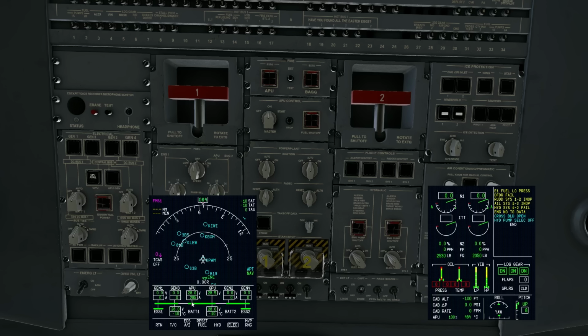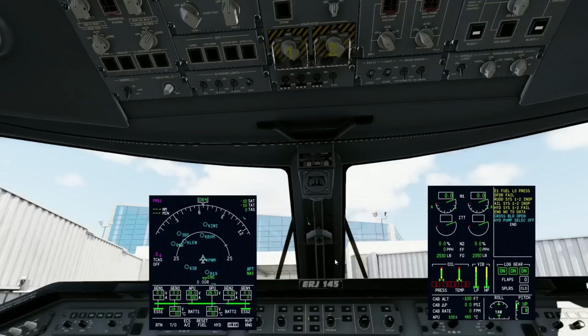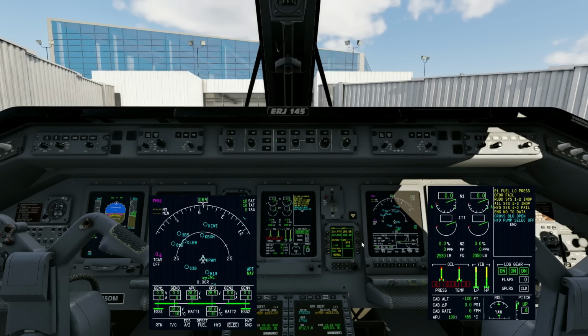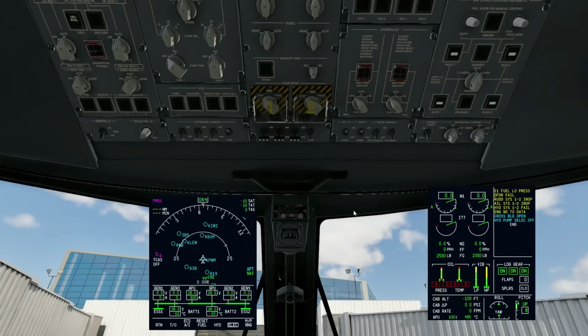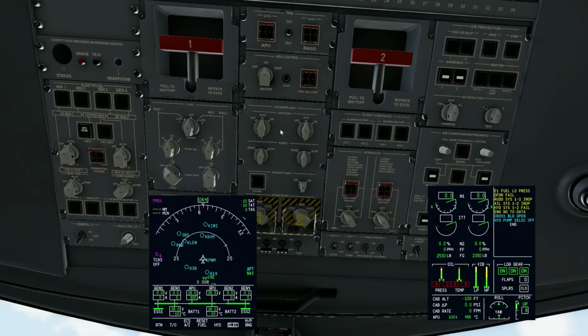Now watch what happens to the electrical load here. So shed bus is off. We're sitting around 260 amps on the APU. The shed bus on, we come up to, we're cruising around 300. When you first start the aircraft, from cold and dark, a lot of systems take a lot of power to get moving. So when you first start it, you'll actually see that with the shed bus on, you get what's called a gen overload condition, APU gen overload.